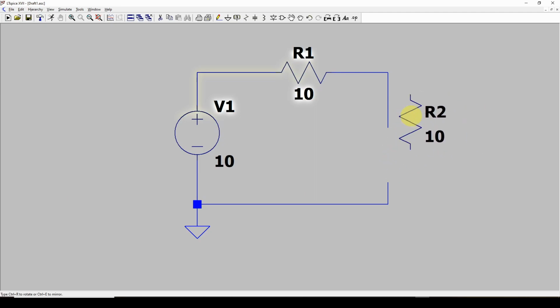Okay, well it allows me to move this resistor. But it's not ideal. So what I'll do is I'll put it back, stamp it back down, and right click, and go up here and try this guy. This is a drag tool. So I'll left click, pick up the drag tool, briefly left click, and so this not only moves it, but it keeps all the attached wires connected. Much nicer. So I drag it to where I want it, left click, then right click to release. So those are the basic tools you're going to use here to set up your circuit, and we'll look at some others a little bit later, but that's the basic